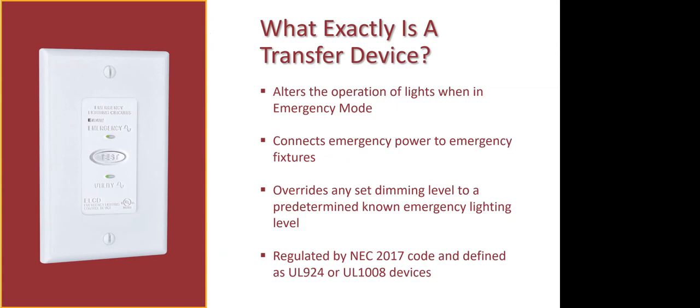Okay, so basically a transfer device, I will summarize as fast as I possibly can. Transfer devices like this one are required by NEC code and UL code. The reason that they're required is, think of it this way. If you go into a room and you flip a light switch or a control, and it's controlling every light in the room, that also means that that control is controlling the emergency lights. Now, if you went into that room and you had the lights on, and then you left the room and you turned the lights off, if there was a power outage and you didn't have a transfer device, that would mean the emergency lights would not come on.